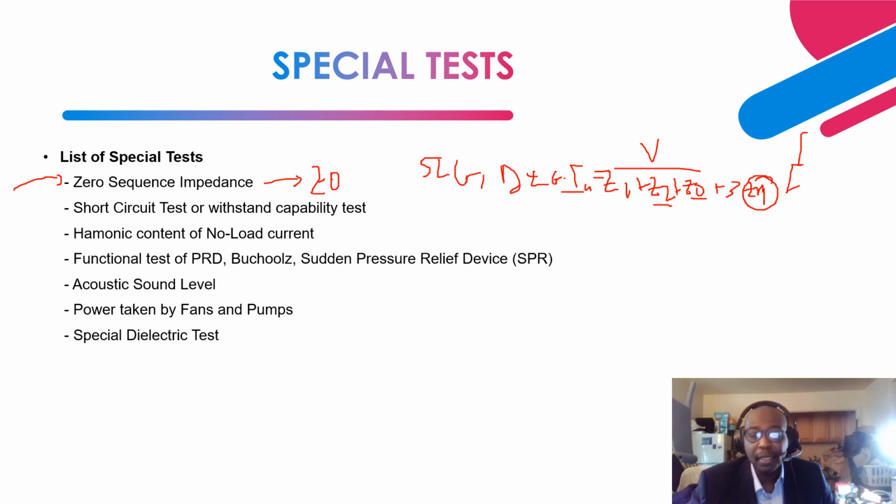If this is the grounding impedance or grounding resistor from the Y side of the transformer, it is 3 times this value. This is shown over here. So that is how the sequence currents are found based on a single line to ground fault.